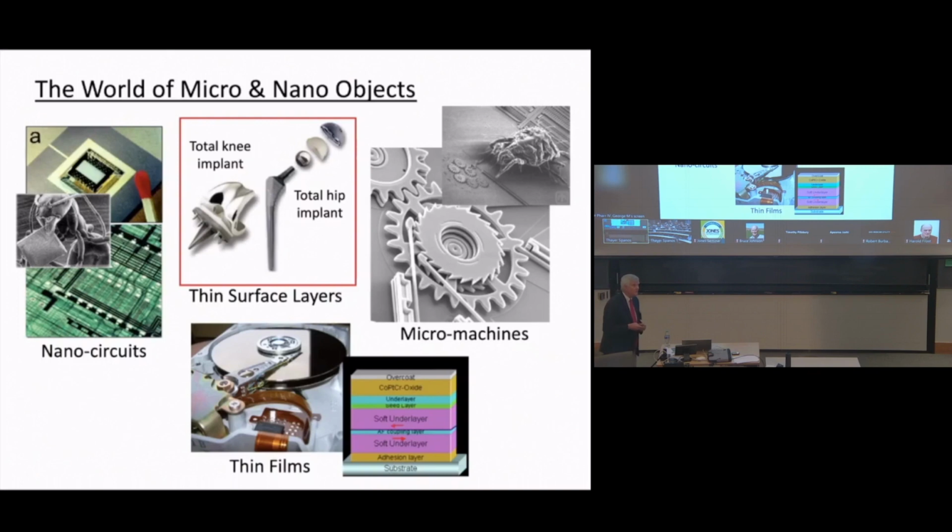And one of the things that you can do to improve the wear resistance of those things is to ion implant the surface. If you can take a piece of steel and implant the surface with ions of things like nitrogen and so on, they go into a depth of just a few microns. And in doing so, they dramatically improve the wear resistance of the material. In fact, the original nano-indenter that was developed back in the 1980s, the purpose of it was to explore the mechanical behavior of those 1 or 2 micron regions in an ion-implanted steel part. And so there are nano things there.